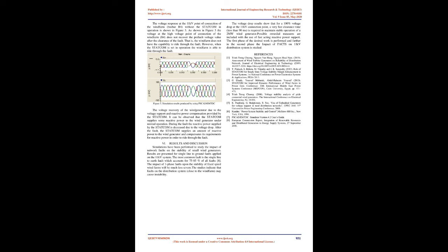A lumped 11 kV/0.69 kV wind turbine terminal transformer with 5% impedance was used to connect the wind turbine to the 33 kV/11 kV network. The computer program PSCAD/EMTDC [7] was used to simulate dynamic stability.